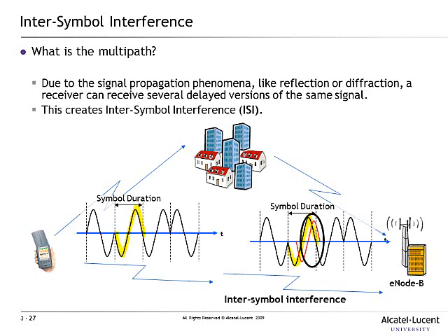The reflected one is going to arrive slightly behind in time, and it may also be of a smaller amplitude, because in the process of reflection you lose some of the electromagnetic energy associated with the wave. So at the receiver you are going to get two waves arriving, and they have different amplitude, different phase, and so forth. And this can cause an error. It can cause something called intersymbol interference, or ISI. Again, this occurs only within one subcarrier, from one symbol to the next symbol within the same subcarrier.